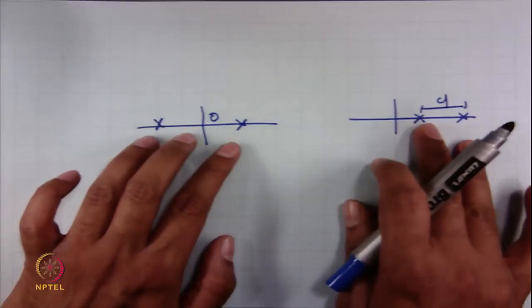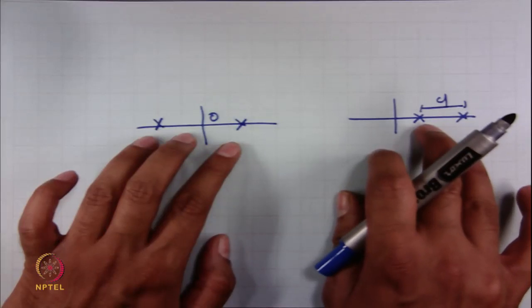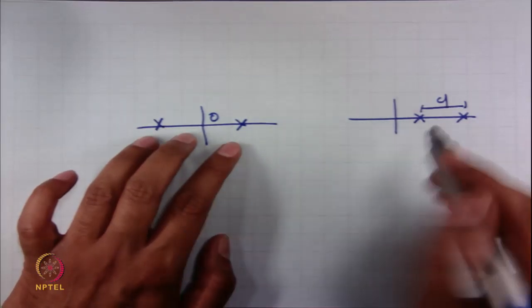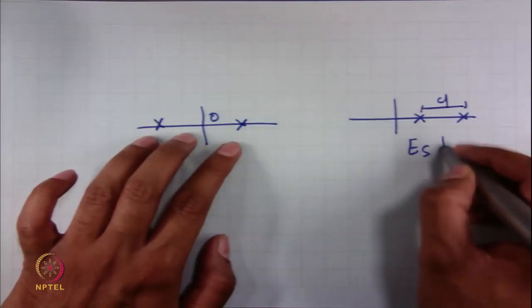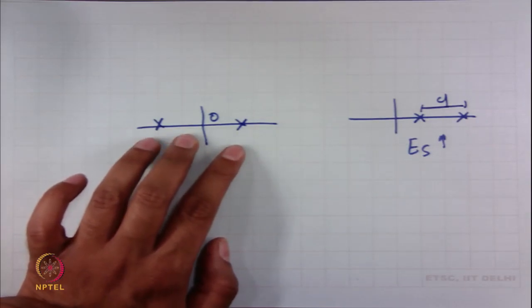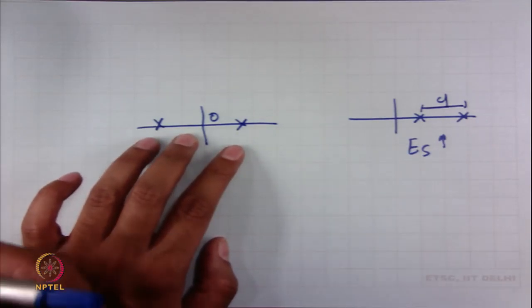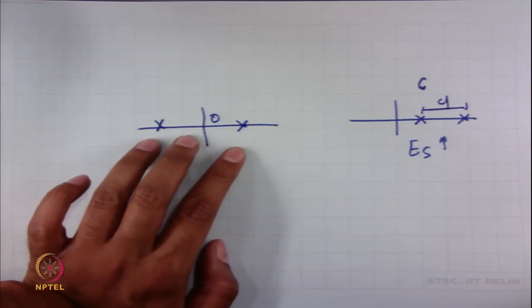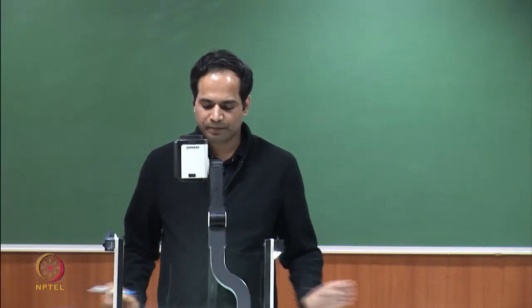So, both these constellation schemes achieve the same BER performance, but this constellation scheme has to spend a higher energy per symbol. And thus, if I want to estimate the performance for the same energy spent per bit, this scheme will have a poorer performance for the same energy spent per bit. And that is what this expression is saying.